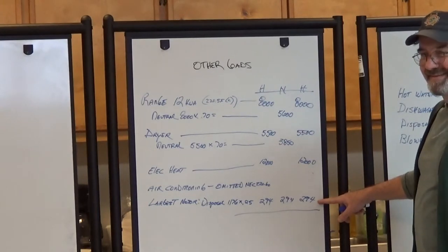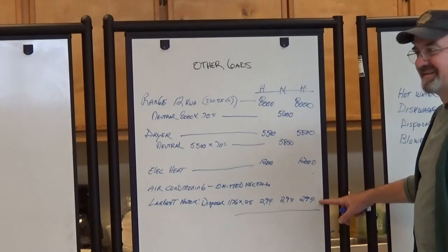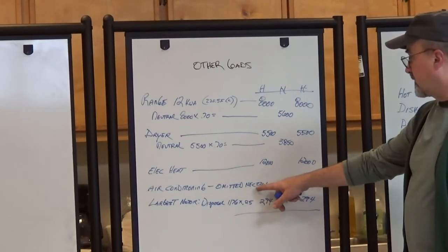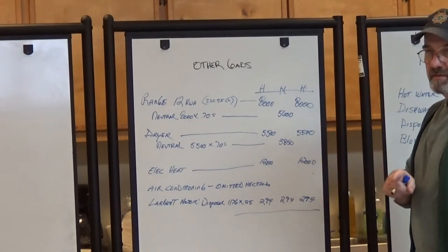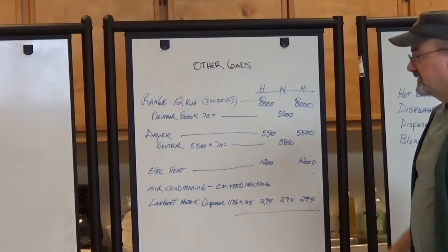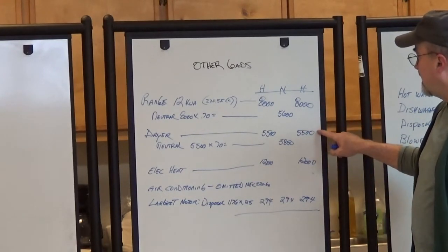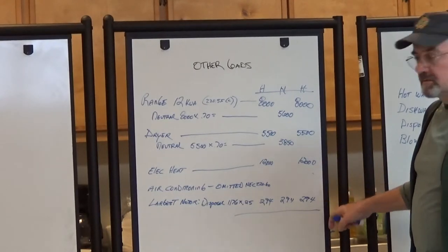That's my mistake. That's for future growth, right? Don't we have the air conditioning though? Not the air conditioning, because of Article 220.60, they don't need the largest of the two. That's why I had that extra 12 on there. Yeah, the largest of the two. So, 25,794. Does that sound right? Yes. Okay.